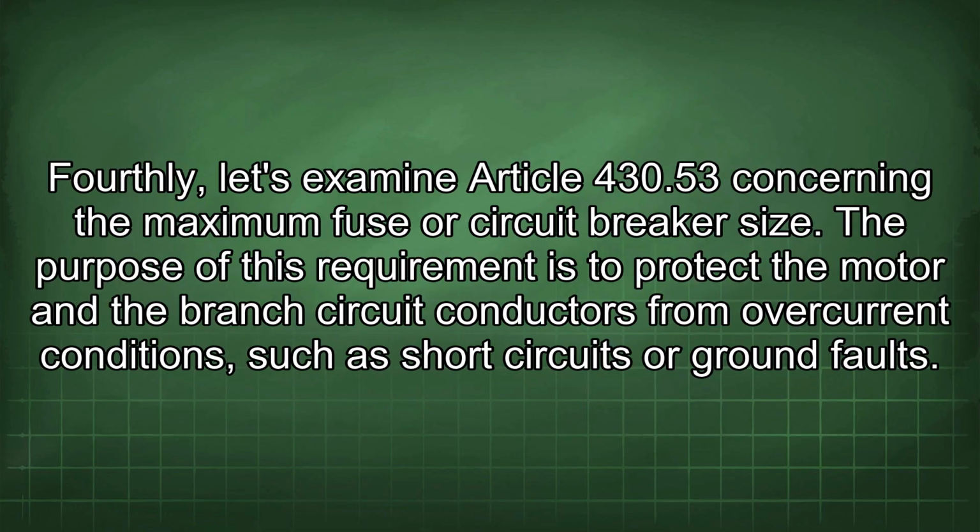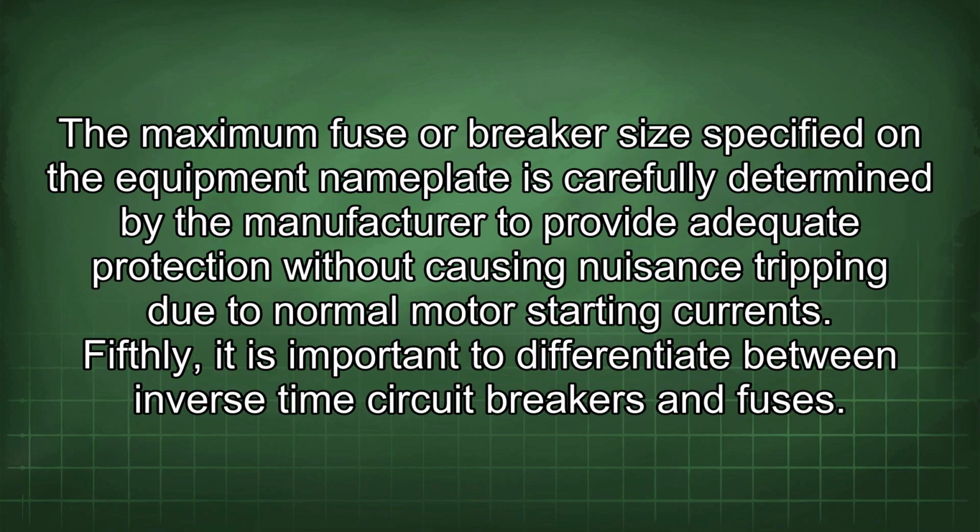Fourthly, let's examine Article 430.53 concerning the maximum fuse or circuit breaker size. The purpose of this requirement is to protect the motor and the branch circuit conductors from overcurrent conditions such as short circuits or ground faults. The maximum fuse or breaker size specified on the equipment nameplate is carefully determined by the manufacturer to provide adequate protection without causing nuisance tripping due to normal motor starting currents.